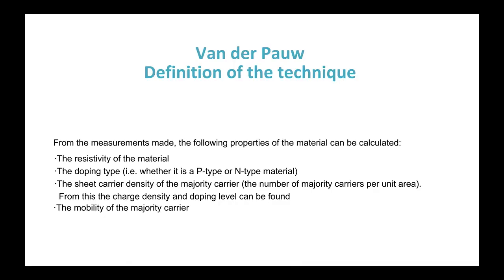Van der Pauw is a technique commonly used to measure the resistivity and the Hall coefficient of a sample. Its power lies in its ability to correctly measure the properties of a sample of arbitrary shape, as long as the sample is approximately two-dimensional, solid, and the electrodes are placed on its perimeter. The Van der Pauw method employs a 4-point probe placed around the perimeter of the sample, in contrast to the linear 4-point probe. This allows the Van der Pauw method to provide an average resistivity of the sample, whereas a linear array provides the resistivity in the same direction.